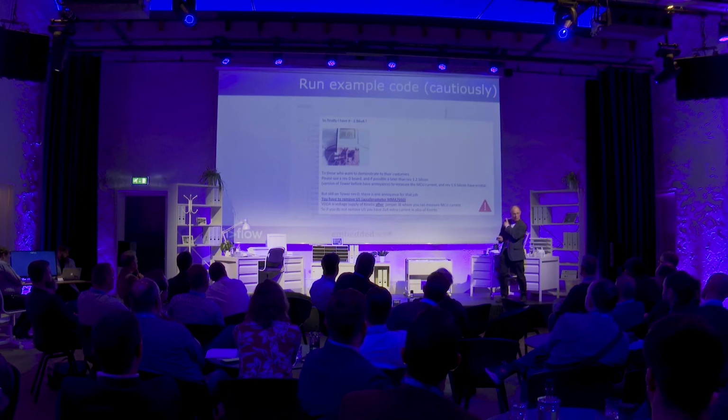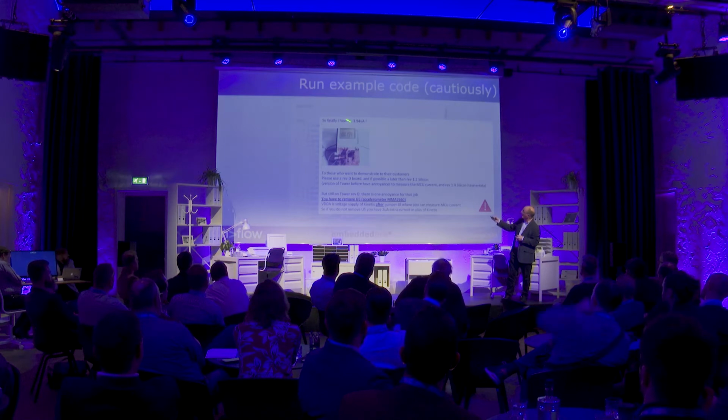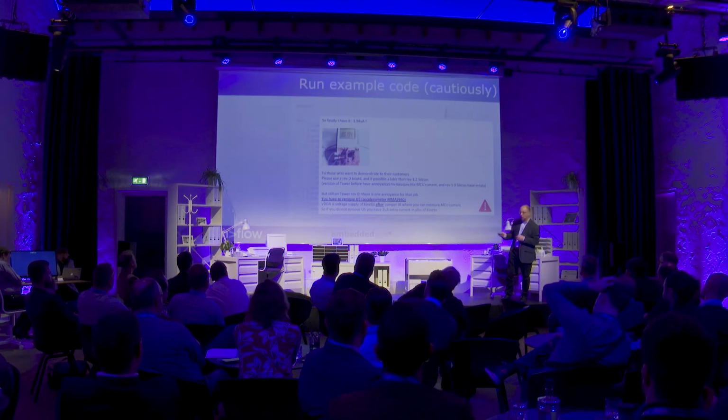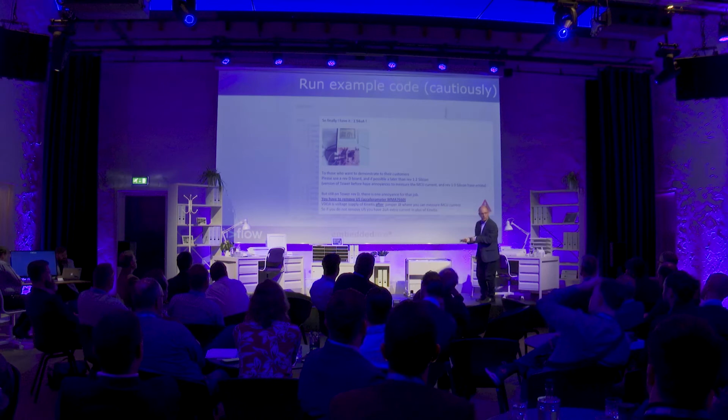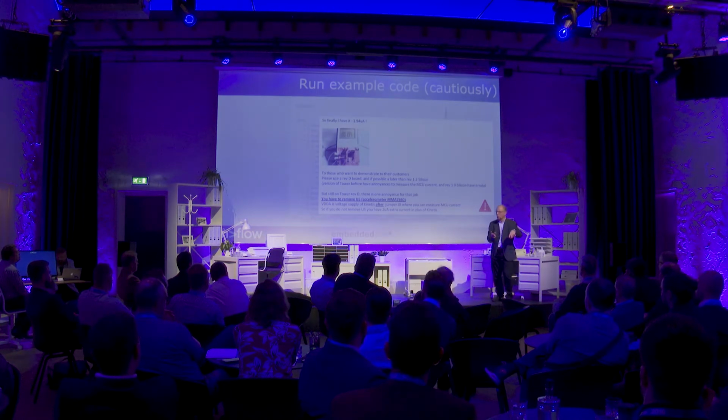Just be careful though. Here's an email I had with an ex-colleague about demonstrating low power modes on evaluation boards. There we are, it's kind of sub 2 microamps was the target. Well, we have to use this particular version of silicon on this particular version of development board. And oh, by the way, you have to take off these jumpers. And if you want to measure it accurately, then you've got to take off the accelerometer. And there's this kind of level converter on the board that somehow takes 70 microamps.